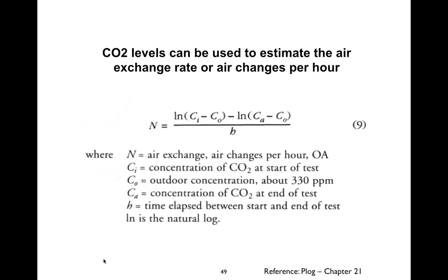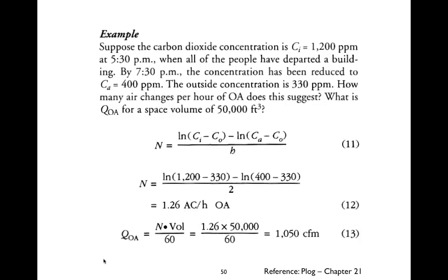So it's tough. You can also use CO2 as a tracer gas. For instance, let's say you have a building that closes at 6 p.m. and at the end of the day the CO2 levels are 900 ppm. You could leave a monitor in there, have the air conditioning continue to run after they close the place, and watch how quickly the CO2 level declines.